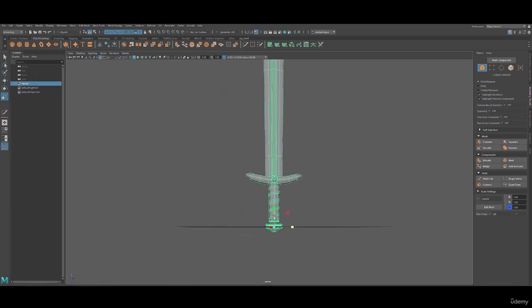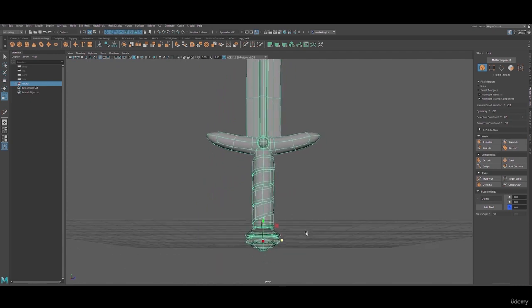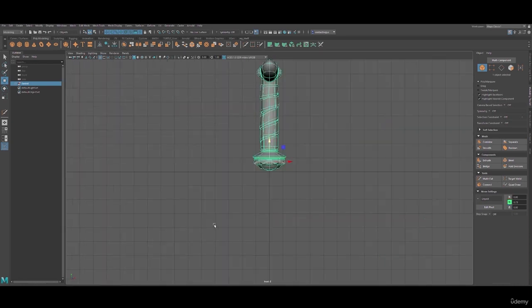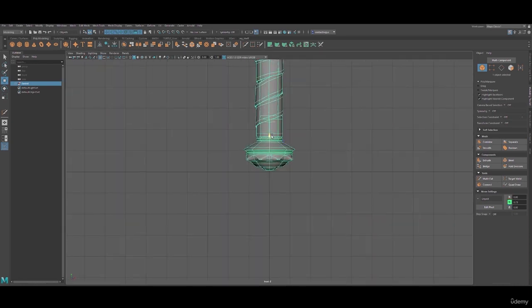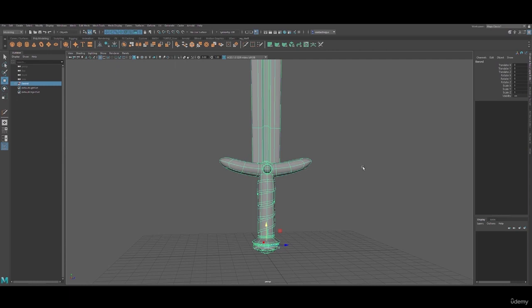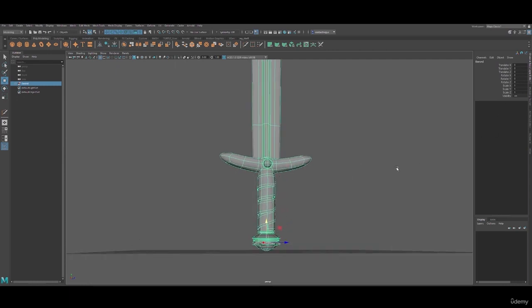Okay, last thing, you can see it has a pivot point. And the pivot point is at the 0, 0 location. But what I'm going to do is bring it up so that it stands actually on the surface on the 0, 0 line. And then I'm going to modify and freeze transformations. So when I type in 0, 0, 0, it's going to locate it in this position.